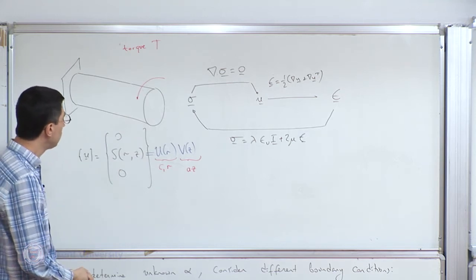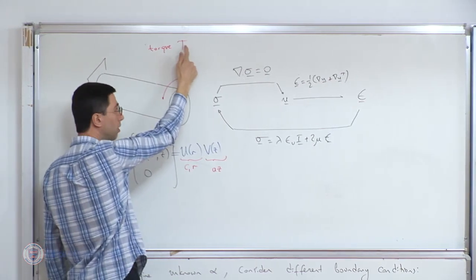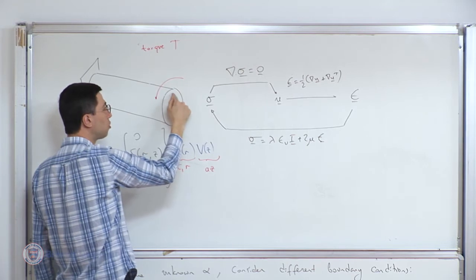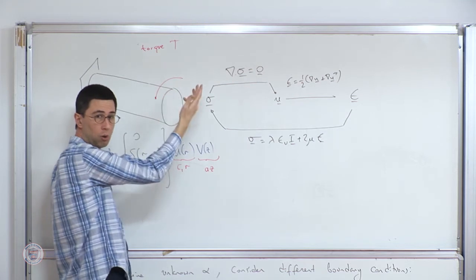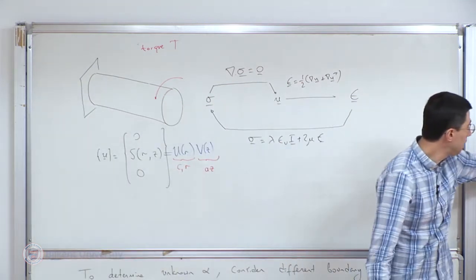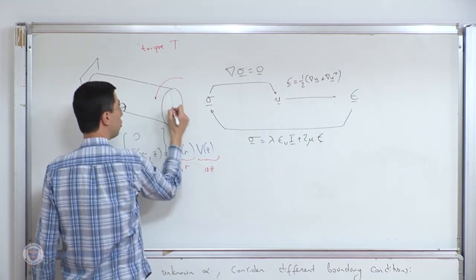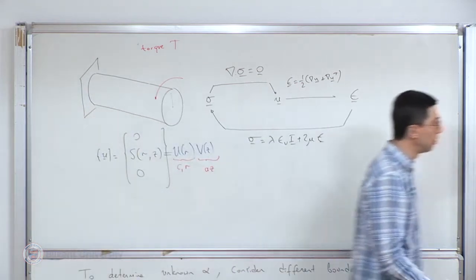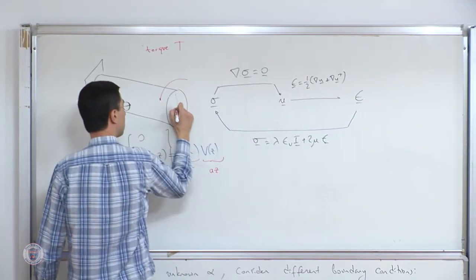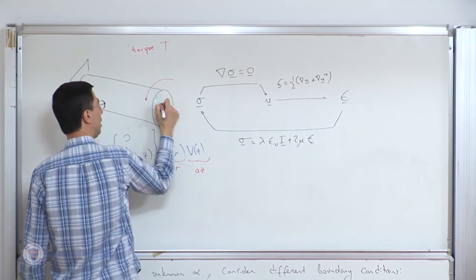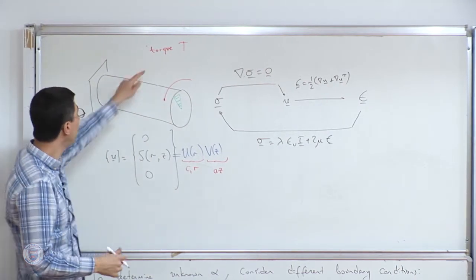What that means is that however I apply this torque, it might be through some strange, complicated distribution of tangential stresses, or sigma z theta in this case. Sigma z theta could be nicely distributed according to the theoretical equation, which is a constant times distance r. That would mean it is linearly distributed. If it's so beautifully distributed, it is our understanding of a pure torque.